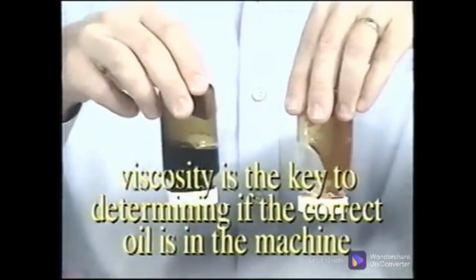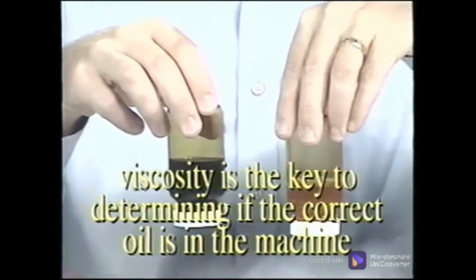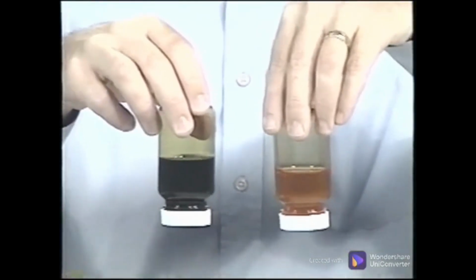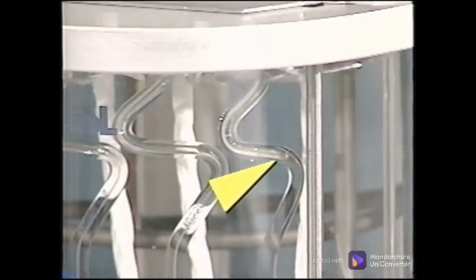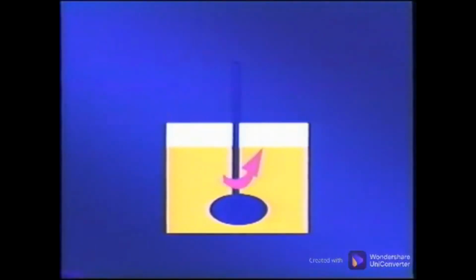The viscosity of an oil in a machine is a key to quickly determine whether the correct oil is in the machine, and on-site oil analysis should have the capability of measuring viscosity. Methods of measuring viscosity include timing the flow through a calibrated capillary tube heated to 40 degrees centigrade or 100 degrees centigrade, timing an object to fall through oil, and measuring the drag on a disc spinning in the oil.